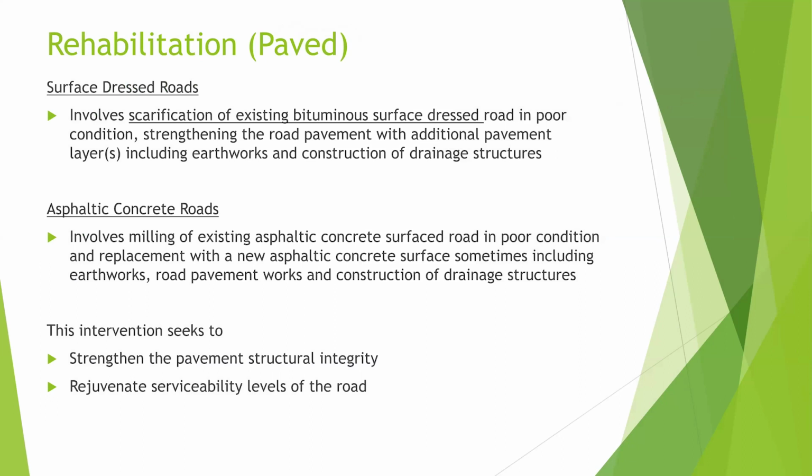Now, the next is rehabilitation on paved roads. Rehabilitation on paved is also a periodic maintenance activity. Now, where I started from, the cost is increasing. Least cost is resealing, then you move to the next, partial reconstruction, the next overlay, and then we have rehabilitation on paved. The rehabilitation on paved can be on surface dress roads, and also on asphalt concrete roads.